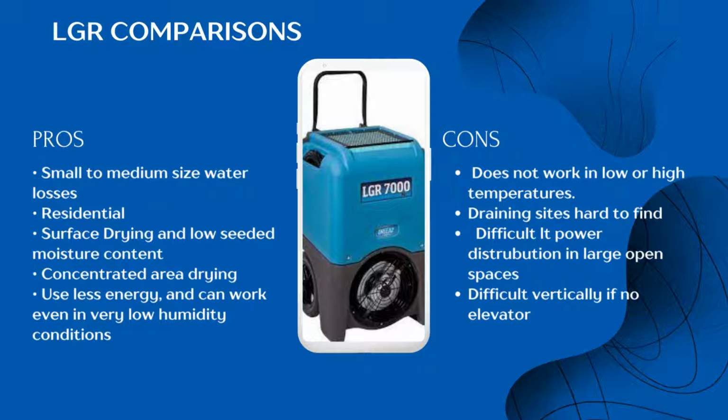LGR comparison. The pros of LGRs are small to medium size water losses are good to use. They're good on residential. They're good for surface drying and surfaces that have a low water content, on low moisture content. They're not the best tool probably for something that's extremely wet, such as a flood job where the water's been pretty deep. It will work. It's just a little bit slower.